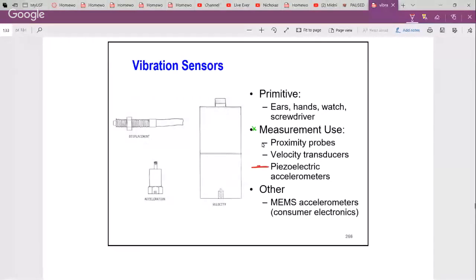For rotating equipment, we can use some accelerometers, but oftentimes we use proximity probes because they're non-contact. We can actually look at rotor or shaft displacement. And as you saw with the balancing kit, the balancing demo, that was what we did. Of course, here are some sketches of a proximity probe, a typical accelerometer, and then a typical velocity sensor that we use. These used to be more common, let's say 2-3 decades ago. They're not so common anymore, but you still see them from time to time.